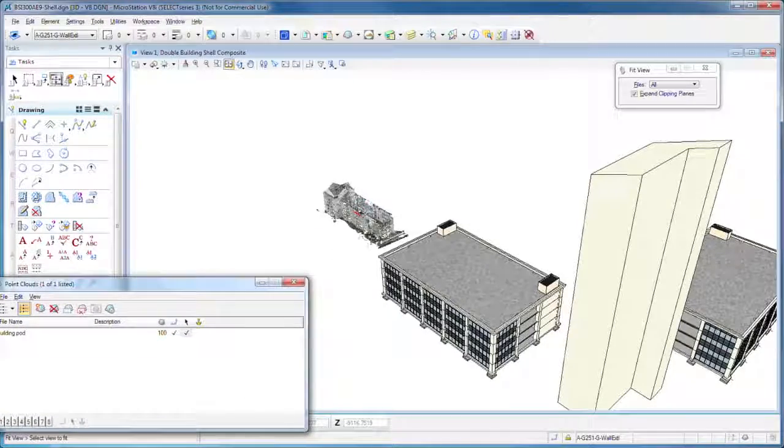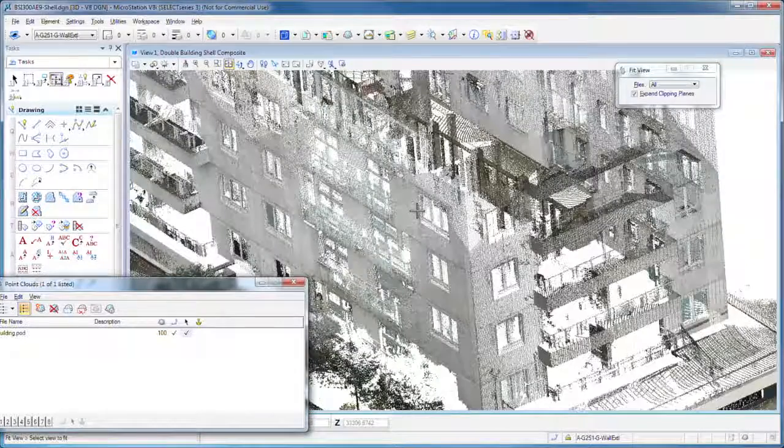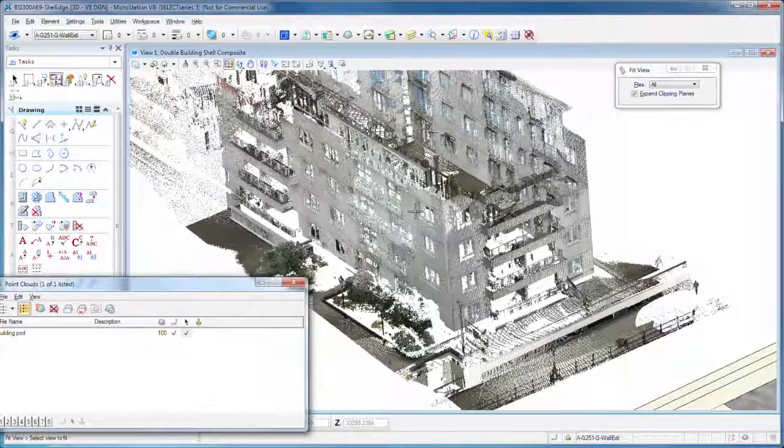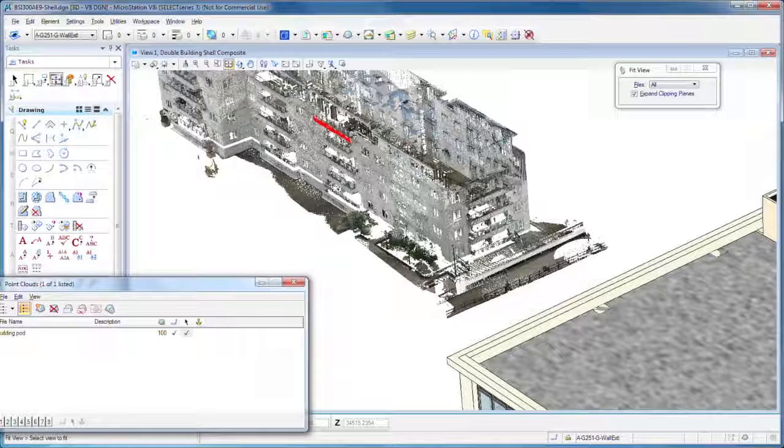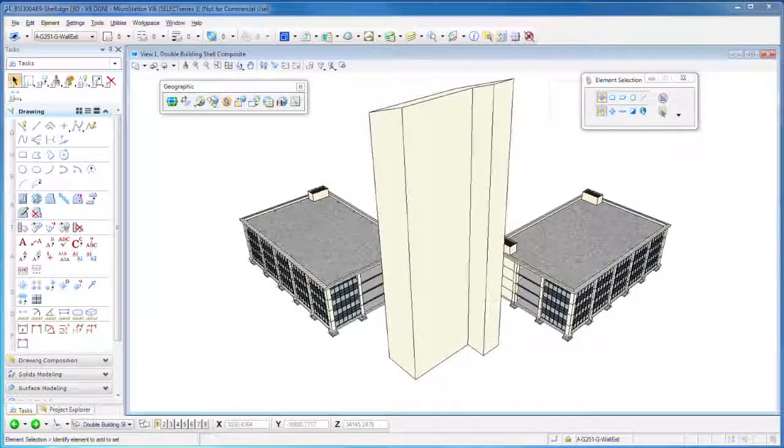So there you go, and we'll click here to get rid of the red, and then we can zoom in on this and take a look at it. You see it's a relatively dense point cloud of a building exterior, because you can see it looks hollow inside. And it would be useful, again, for context. And that's what it's used for more and more, like in factory rehabilitation projects or renovation projects, or in a process plant, taking out a piece of equipment, putting in others. Rather than do a 3D model of the whole plant, simply go in and scan it and get a point cloud, and then build your actual new work right inside, erasing points and things of that nature. So that's point clouds.